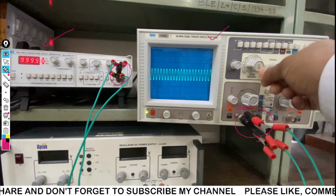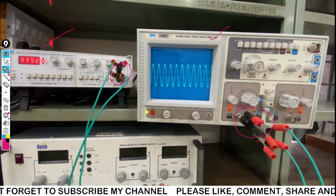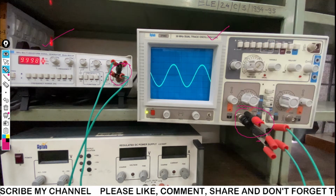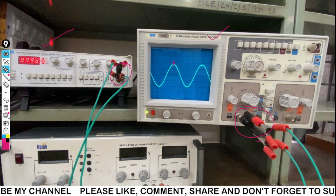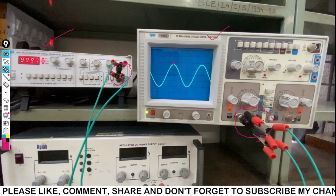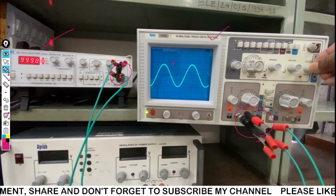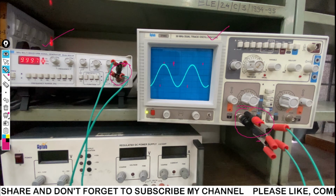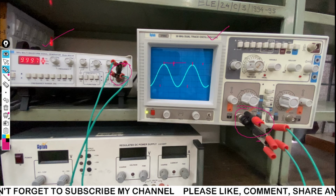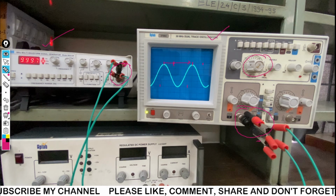We have to adjust it by using voltage per division, and we have to adjust the time scale by using time per division. You can see here sine waveforms are shown. So we have to adjust so that we can at least see two crests or two troughs to measure the actual frequency and measure the voltage. We have to adjust in such a way that this crest is at one part, and then the next part will be available here. We can measure the distance between these two, and using the time base knob we can calculate the frequency.